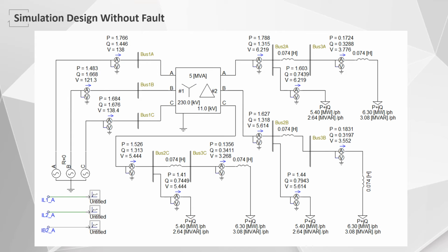The distance between CT and relay is used for the selection of the secondary current transformer. At relays 1, 2, and 3, 5 meters was assumed because the distance between CT and relay is short and they are supposed to be on the same switchboard.